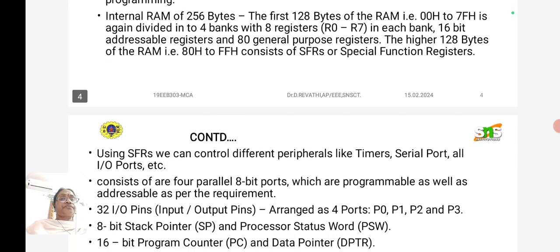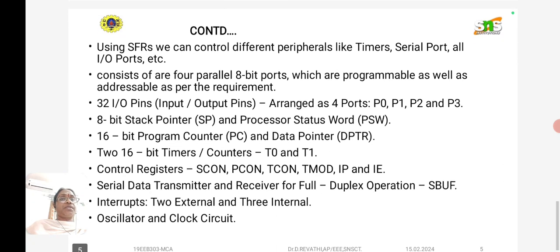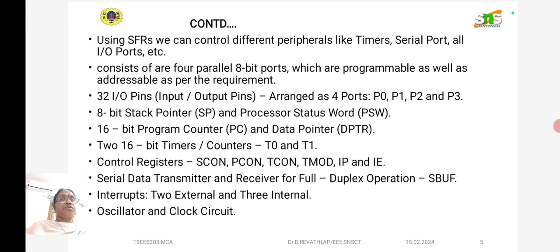Using the SFRs, we can control different peripherals like timers, serial ports, all IO ports, etc. It consists of 4 parallel 8-bit ports which are programmable as well as addressable as per requirements. It has 32 IO pins, that is input output pins, arranged as 4 ports P0, P1, P2, and P3, that is port 0, port 1, port 2, and port 3.